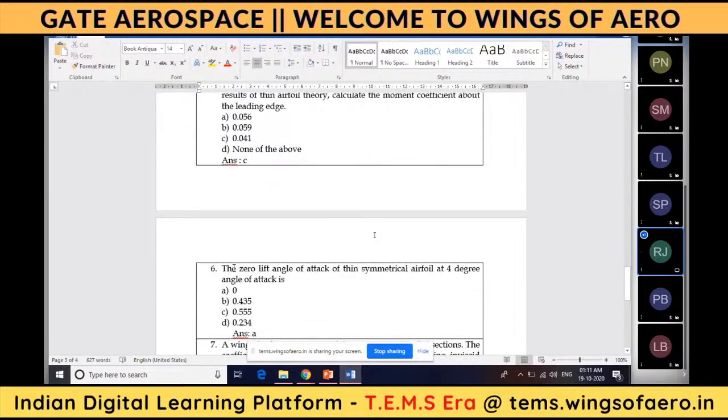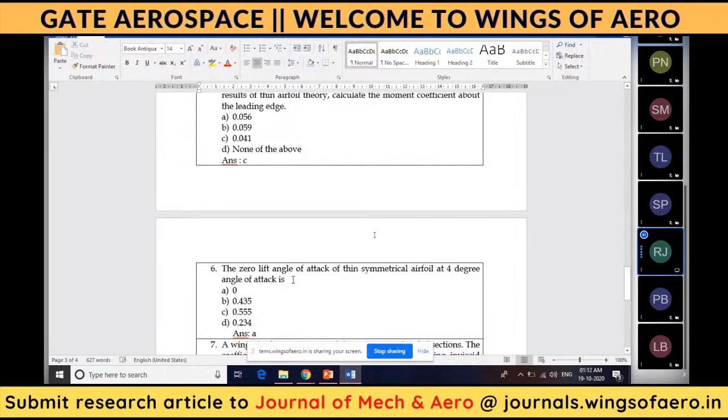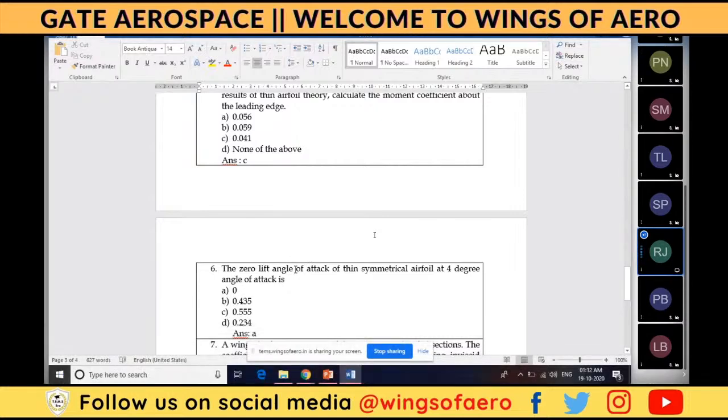See here, the 6th question. The zero lift angle of attack of thin aerofoil theory at 4 degree angle of attack is, the answer will be 0, because for a thin symmetrical aerofoil there won't be any zero lift angle of attack. Only for a cambered aerofoil will we have a zero lift angle of attack. Therefore, the answer will be 0.